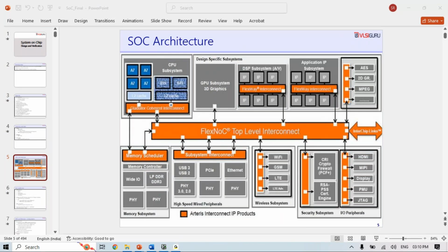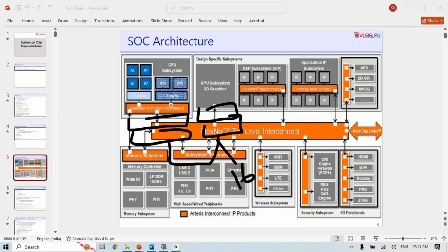See what happens, just to draw here: die to die adapter layer, physical layer, die to die adapter layer, physical layer. They basically negotiate what link width they work at. There are different packaging technologies. One is called standard packaging, which only supports 8 lanes or 16 lanes.